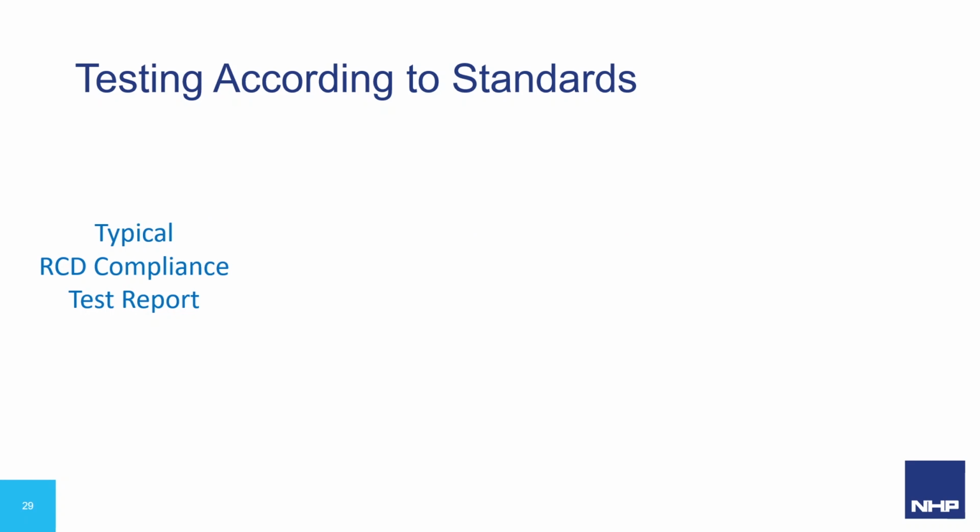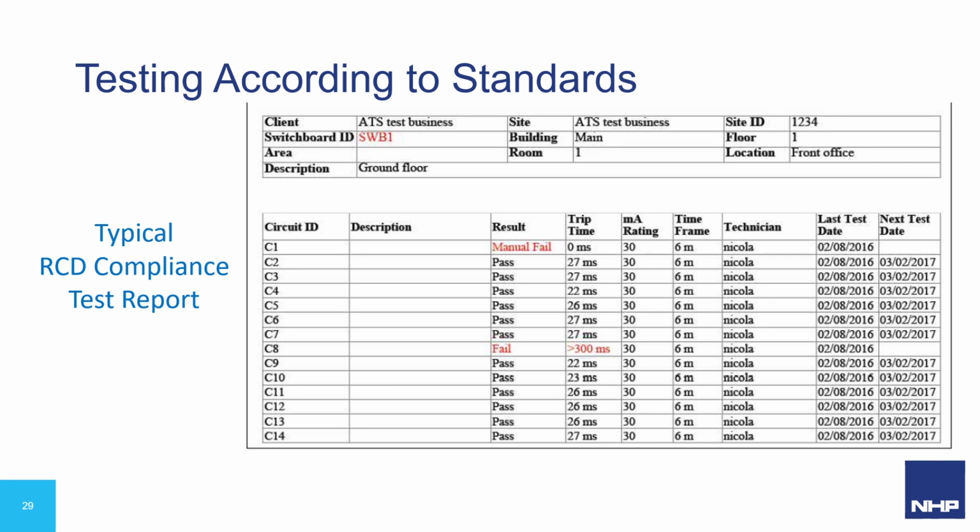This attached table is a typical report requirement outlining the identification of the workplace location, the RCD tested, the time, the date, the method, and the result, as well as the qualified person doing the test. Should there be an accident requiring investigation by the authority, it's essential that this type of record is up to date and factual. Incidents requiring investigation and handling by the judicial system may insist on this documentation in the liability process as part of Workplace Health and Safety Act.